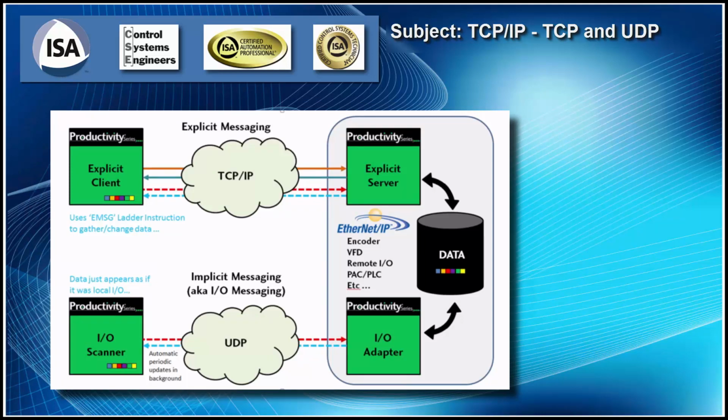So we can see here from this diagram, anything using Ethernet IP basically is the same thing, whether using Rockwell or whoever. We use TCP for messaging. Say I want to send a message. Say I got a bunch of data and I want to send it to another PLC. Well, I use TCP IP to make sure it does actually get that message and it's correct and all the data is there. But if you look at the bottom of this here, you'll see UDP. And when you connect to the I/O adapter, not always you have to pick this, but typically you'll pick what's called implicit messaging.